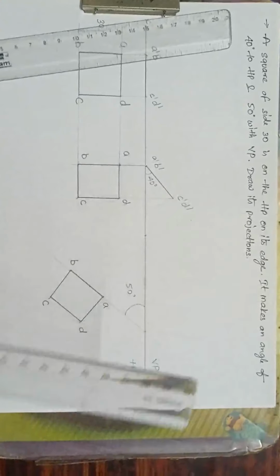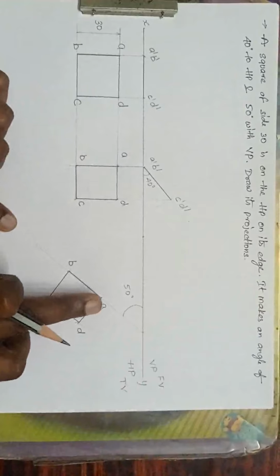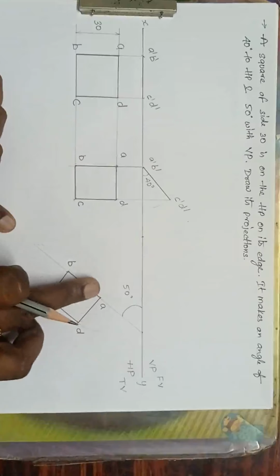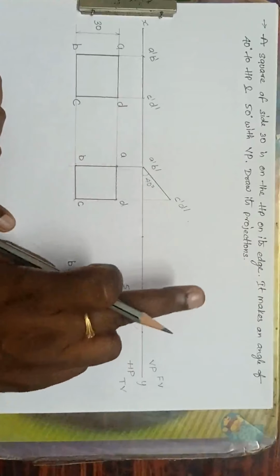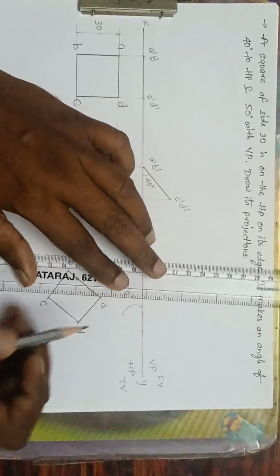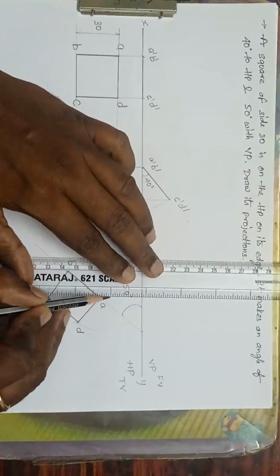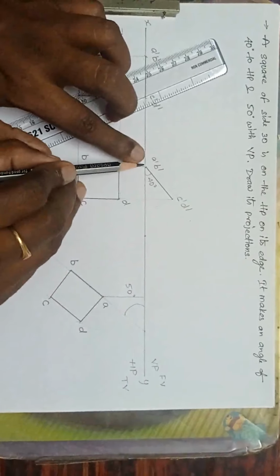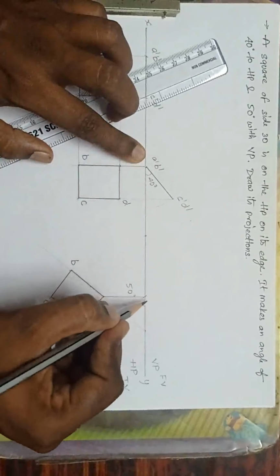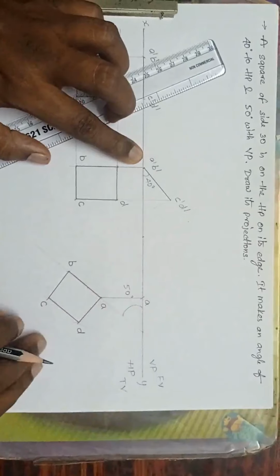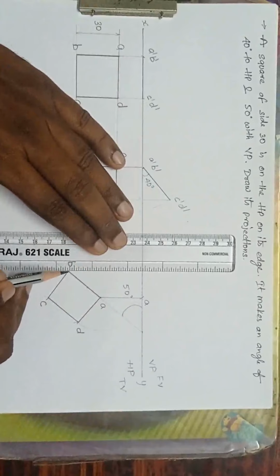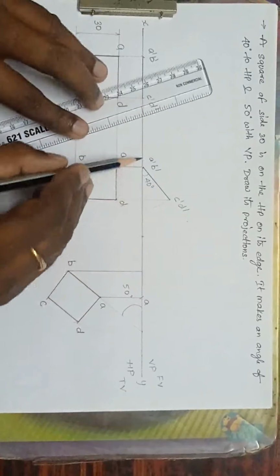What I'll do is drop each and every point, from each and every point perpendicular and parallel on the VP. I have to draw this position now. Now from A, drop the perpendicular line up to A dash B dash. See here, here it is A dash. So the combination of points, this is A. Fine. Next what I'll do, from B, it should be perpendicular line. See, this is the B.